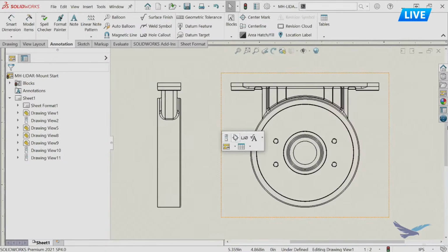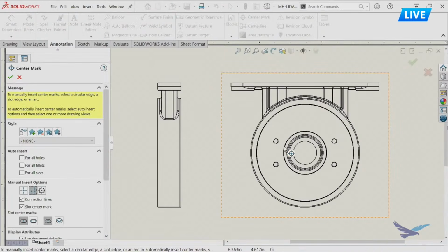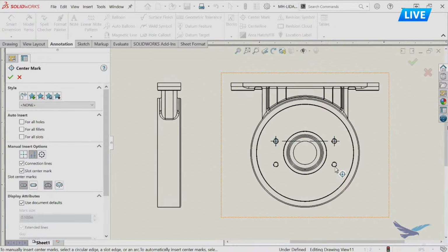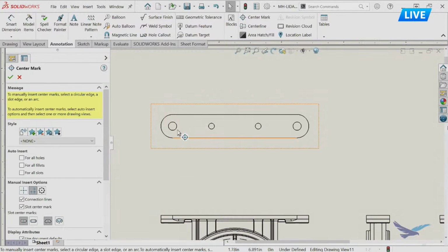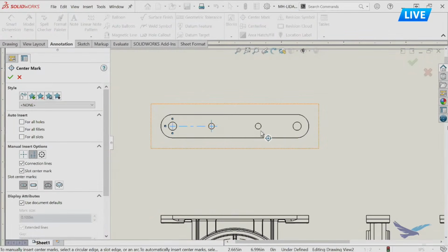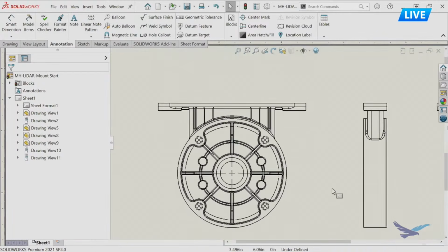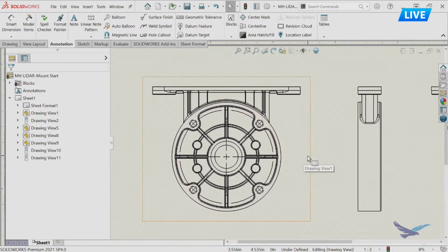And if I want to do a slightly different pattern over here, force the linear connection lines to create something like a rectangular grid pattern. Basically getting these in first is going to make it a little bit easier for me to dimension and also get a cleaner looking result in the end, because all the dimensions will be gapped off the center marks correctly. Hey, Ryan. Yes. Is it possible to directly dimension to those center marks? Yes, yep. So you can pick the center mark, and it's a bigger target than trying to click a small hole too, for instance. So yeah, that's a great point.